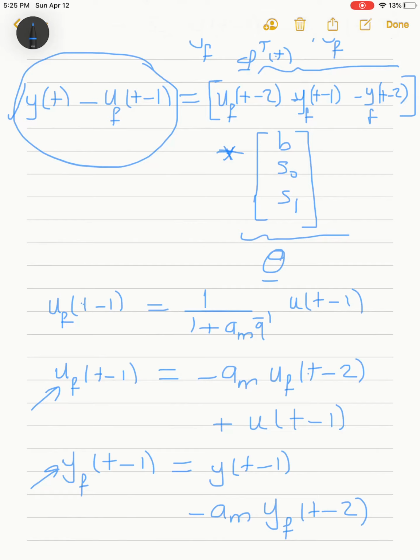It would be equal to the reference model numerator polynomial times the observer, divided by b minus. In our problem here, b minus is equal to 1, and it is given that Bm is just a constant, small bm, and the observer polynomial is q, corresponding to A0. So that will give us bm times q.